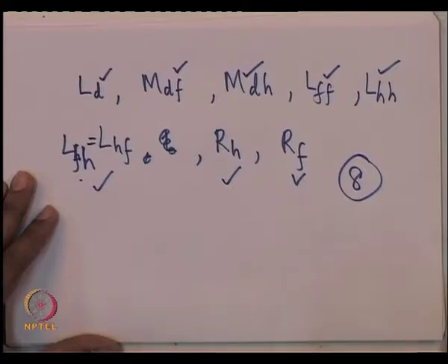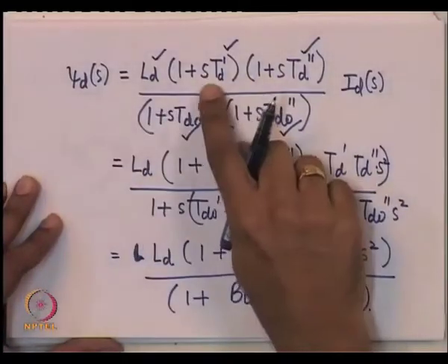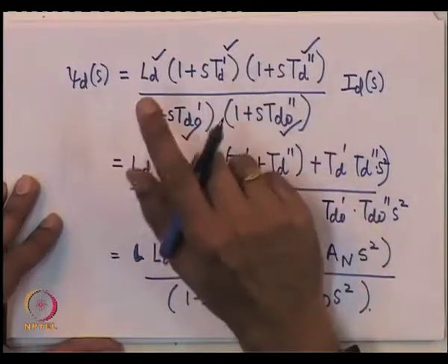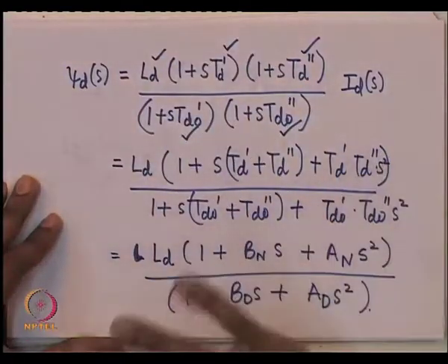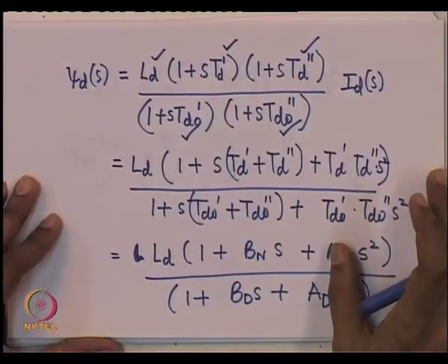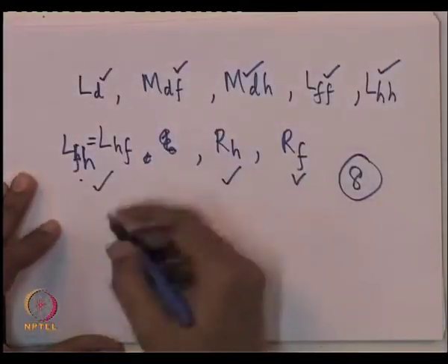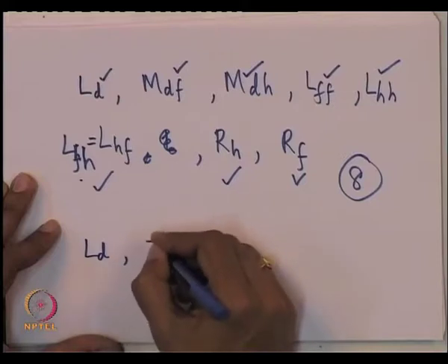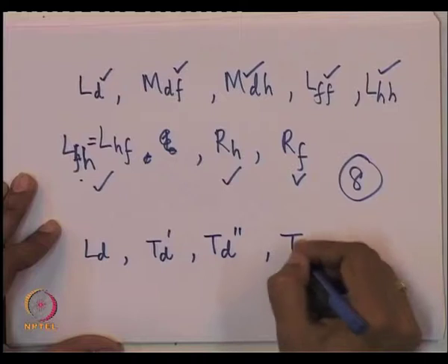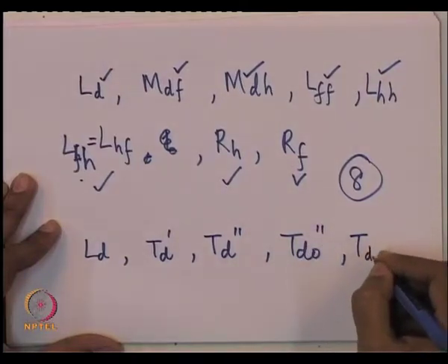Okay. By doing the tests, we can fit the experimental data and obtain, or rather tune, the time constants, so that they fit very well with the experimental data. Okay. So, we will try to tune these parameters. Here you have got 1, 2, 3, 4, 5. So, actually from the tests you will get the parameters of the transfer function.